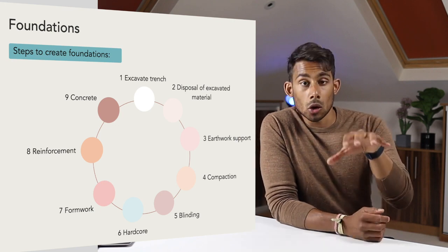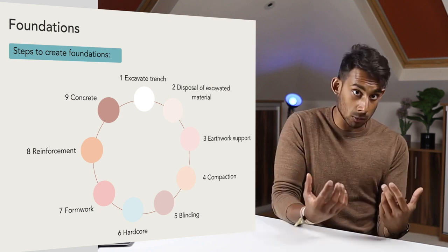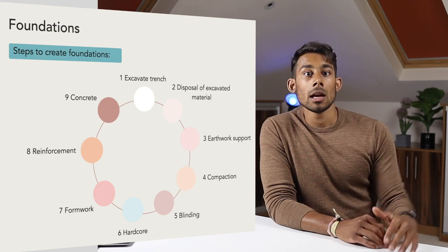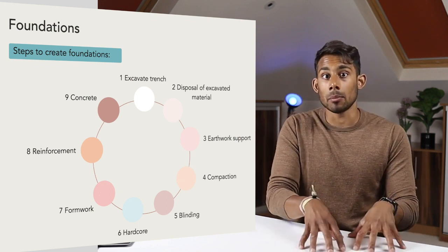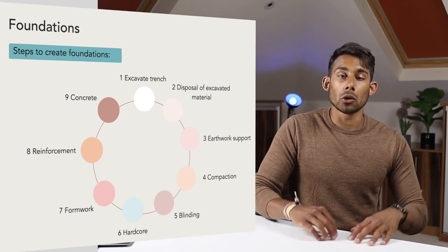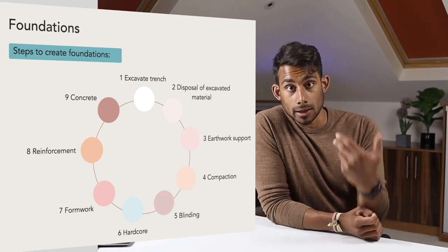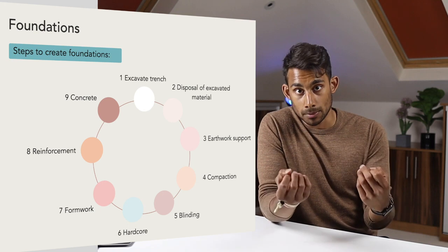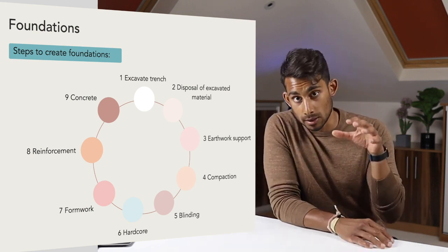As a result, the concrete will need to be unloaded and leveled as quickly as possible. A rake or shovel would be used to move the concrete around and roughly level it, and a straight edge piece of timber to tamp down the concrete and eliminate any air pockets. The concrete is usually wet enough that it could be pulled around the trench using rakes before the surface is leveled out and tamped down to remove any air trapped. This is most efficiently achieved using a suitably sized vibrating poker.